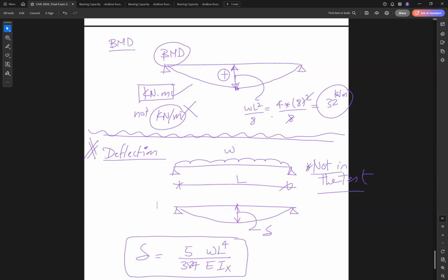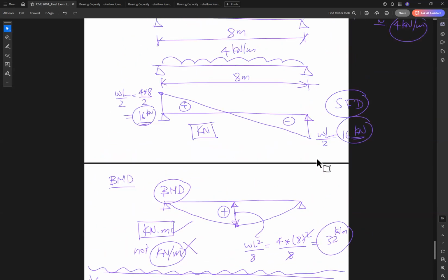So now we know how to calculate the load on the beam, how to find the load combination, how to draw bending moment and shear. For the superstructure, all we have to do is find the wind load, dead load, and live load of whichever member you've chosen, the beam. Then go to the load combinations, choose the highest downward and upward one, and from that draw the bending moment diagram and shear force diagram.